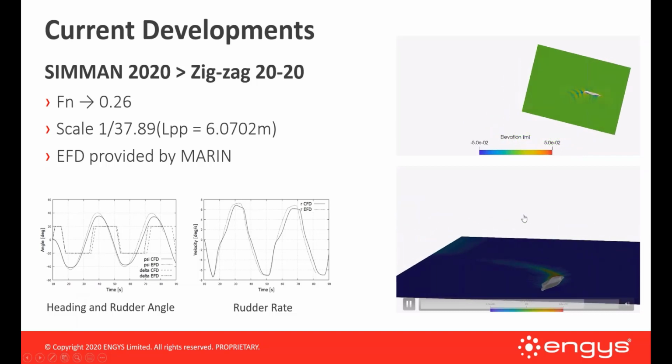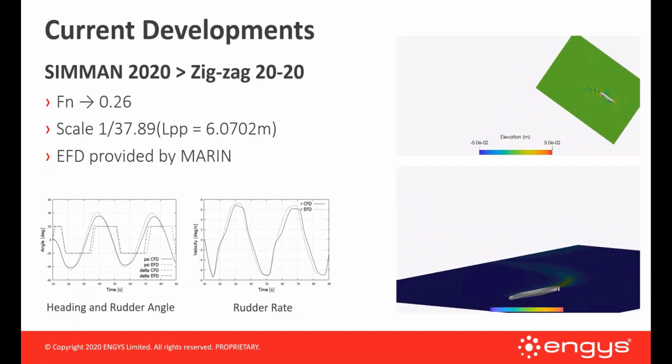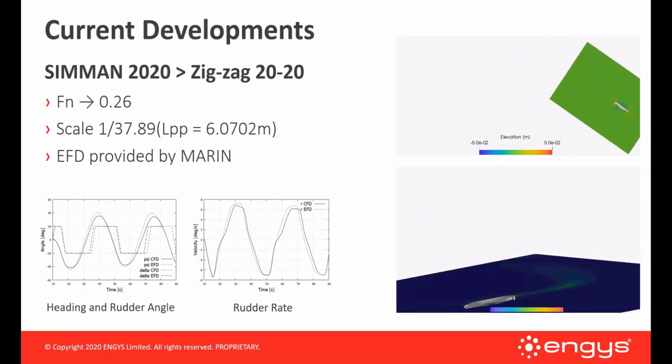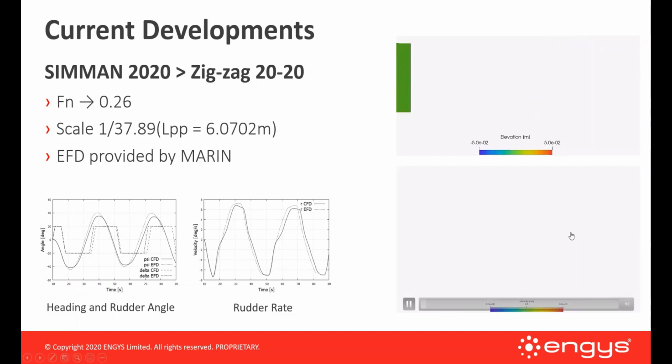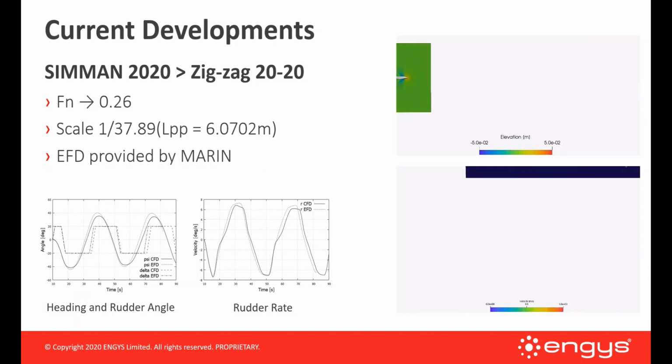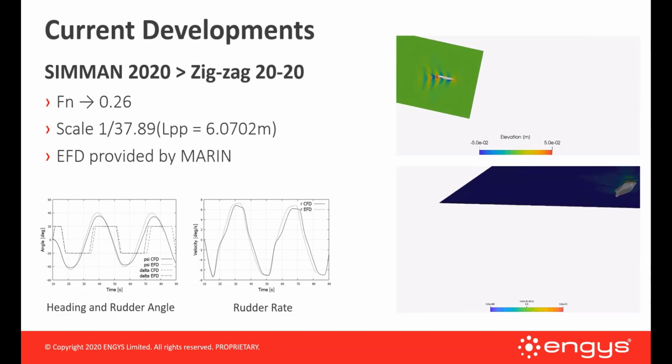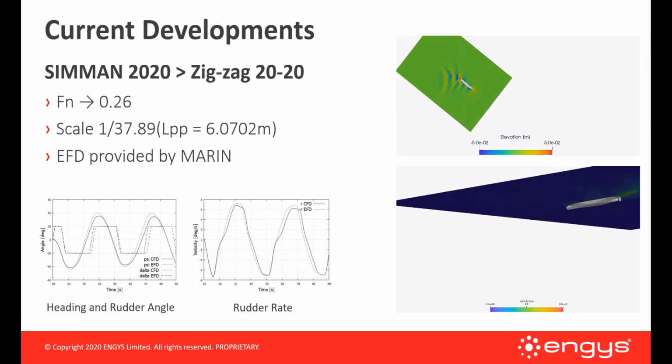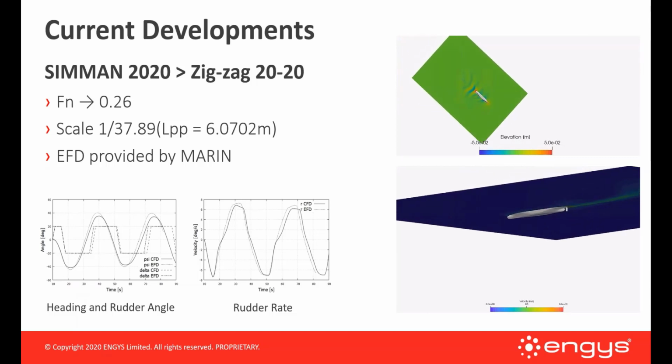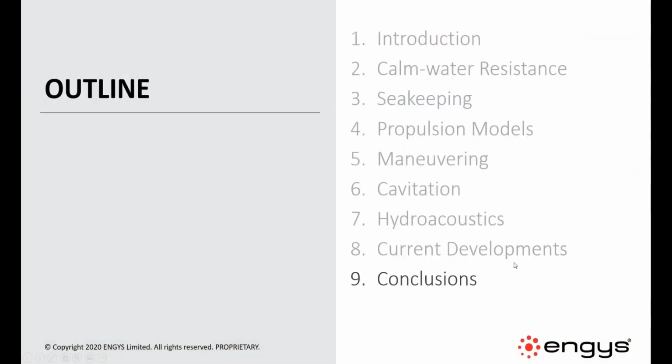And finally, we employed a brand new propeller model based on a response surface methodology. So we have a training set of different conditions for the creation of this regression model for the propeller itself. So it's kind of a non-conventional propeller model.